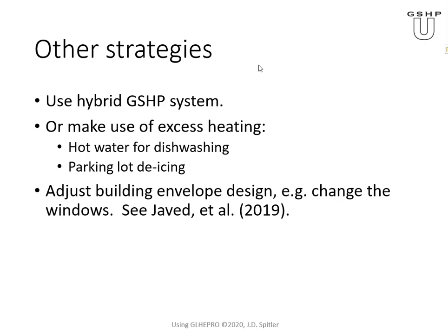Yeah, that should be correct, assuming the U factor of the window is the same. You decrease the solar gains and you'll get lower cooling loads and higher heating loads. So it could be that in that location there's more flexibility to do that, and I have not gone into the EnergyPlus file to see what solar heat gain coefficients are used, but that could be an interesting thing to check.